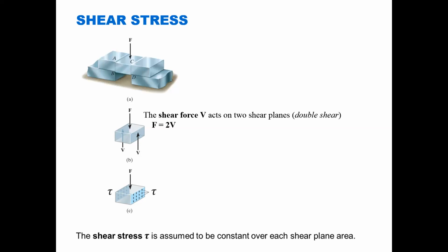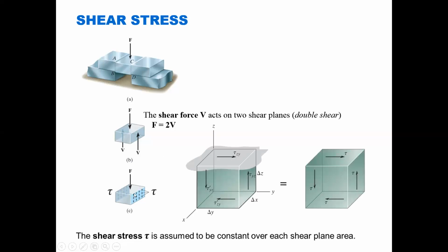Okay, so let's come up with an equation for the shear stress in this particular case. We know it's related to the shear force. And so let's begin to look at an individual area on this face like we did before. What I've blown up here is a face. We envision a little cross-sectional area here on this face.